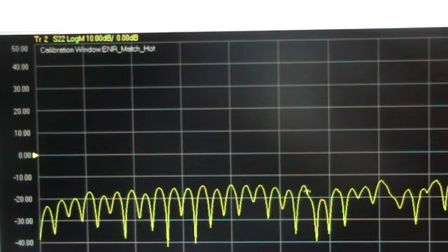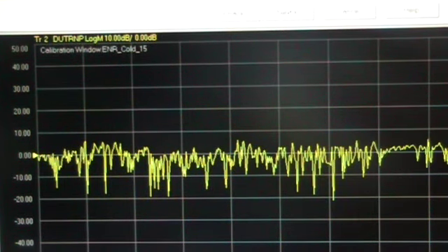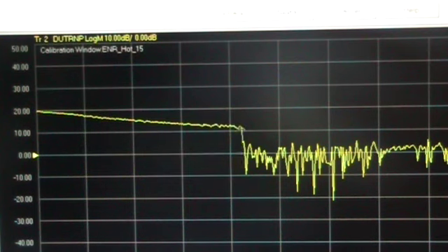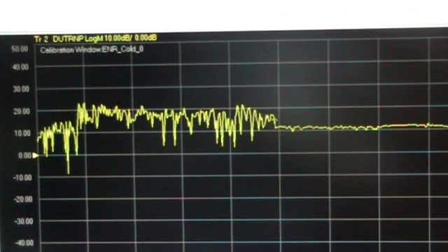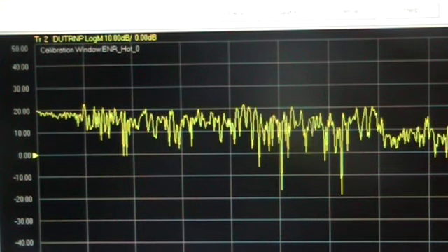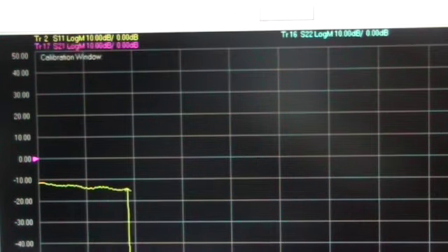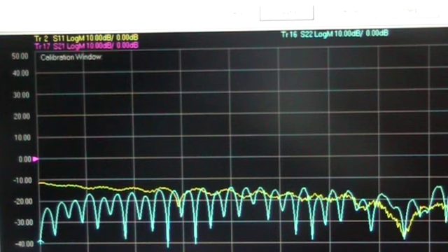And because the system doesn't know what level you're going to have it set at, and they want to allow you to be able to change that during your measurements, they go ahead and just calibrate all 3 of these at once. We always have it set to 30 dB of gain internally, and have never had any problems at all with overloading the front end. You'll definitely know if you do.